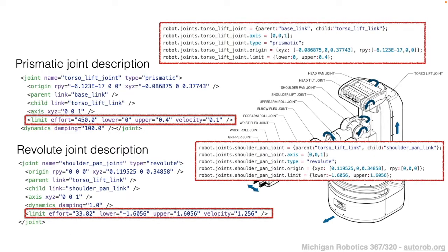In our course, we also have the ability to consider joint limits for the robots. For example, for the Fetch robot or the PR2 robot model, we express the joint limits as a property of a particular joint within our JavaScript version of URDF. Implementing forward kinematics for these physical robot models is optional for this course. But if you do choose to implement the forward kinematics to work with the Fetch and the PR2, I suggest that you consider these joint limits and incorporate them into your forward kinematics to ensure that you don't apply transforms that would exceed these limits.